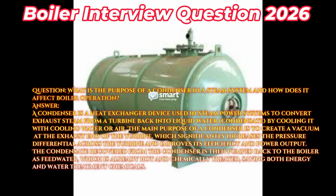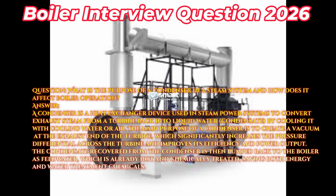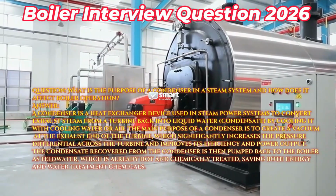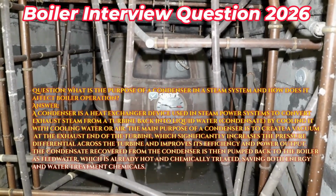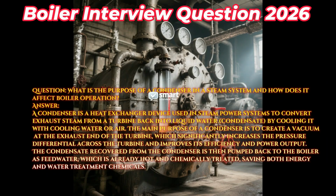Question: what is the purpose of a condenser in a steam system and how does it affect boiler operation? Answer: a condenser is a heat exchanger device used in steam power systems to convert exhaust steam from a turbine back into liquid water, condensate, by cooling it with cooling water or air. The main purpose of a condenser is to create a vacuum at the exhaust end of the turbine, which significantly increases the pressure differential across the turbine and improves its efficiency and power output.